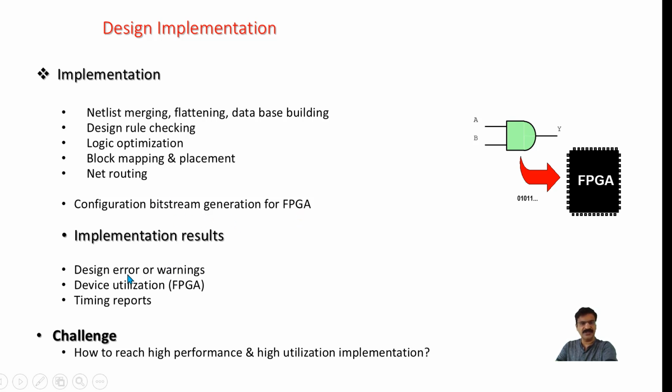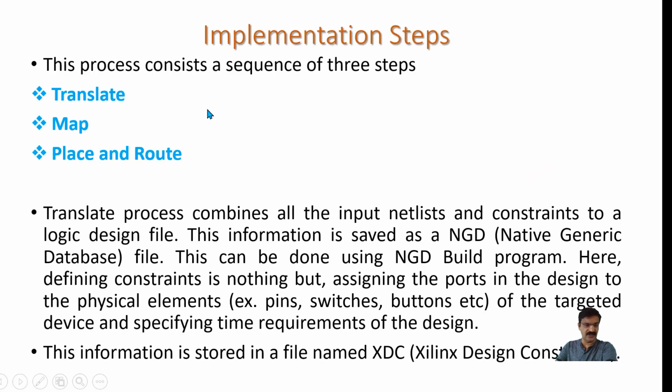And configuration of the bitstream for FPGA implementation results. Check for design errors, warnings, FPGA utilization reports, timing reports. The challenge is how to reach high performance and high utilization in implementation. So you have to write particular synthesis constraint commands to achieve this. So we'll learn all those things.